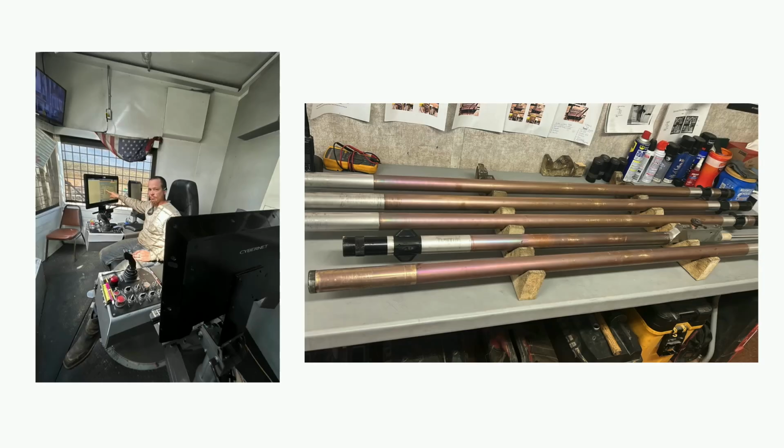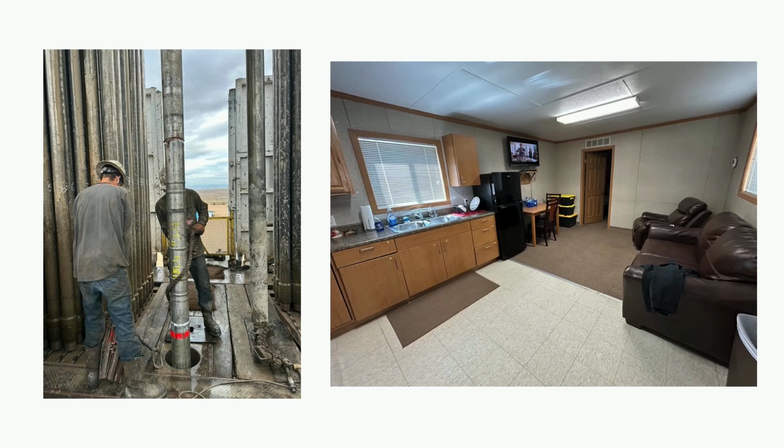And on the right is another picture of the tools. You can see the dipole there, the second from the bottom, 2 batteries and electronics. So part of my job is to maintain those tools. You take the actual electronics out, change out your O-rings, change out your batteries, make sure the dipole itself has good connections. And if anything needs to be rebuilt, you do it all out in the field. There's a picture of them making up one of the Monels, getting ready to stab the tool inside there.